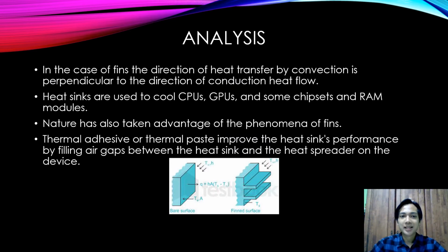Hi, my name is Nazran. I will explain about analysis. Fins are used whenever the available surface area is insufficient to transfer the required quantity of heat with the available temperature gradient and heat transfer coefficient. In the case of fins, the direction of heat transfer by convection is perpendicular to the direction of conduction heat flow, as we can see here in the picture below.